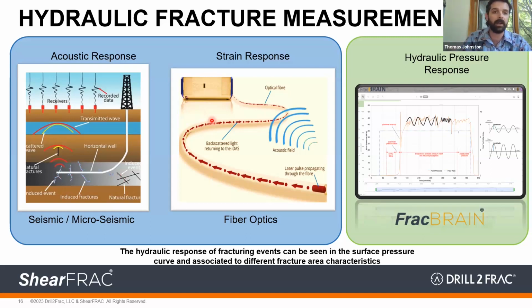So what we've created is this new measurement in the industry, this hydraulic pressure response measurement. It's relatively simple in its setup: we have our own pressure transducers and we just put that on the wellhead. We're looking at that pressure response on the active well and interpreting how that hydraulically connected wellbore all the way through to the rock is actually breaking that rock up. So we're looking at breaks in the rock based on how much pressure build up and how much pressure fall off we have.